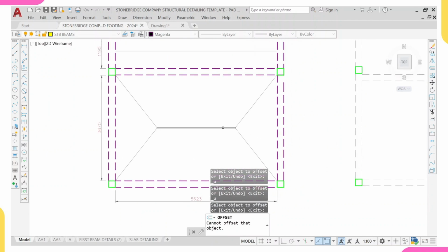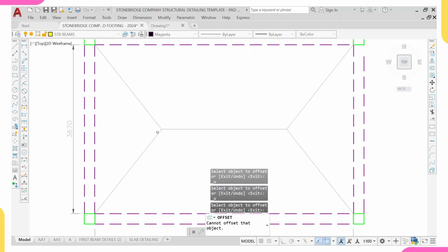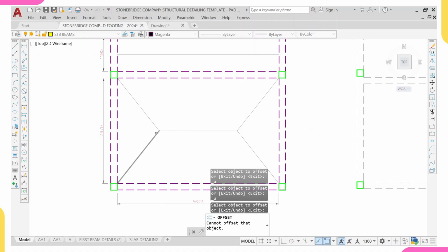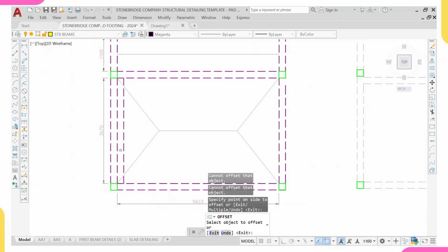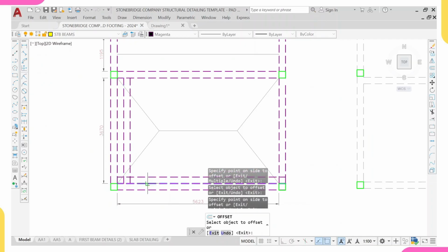So in a two-way slab, all the beams, this beam, this beam, this beam, this beam, are all carrying load. That's why in a two-way slab, in all directions, we will place main bars. But the bar that will be at the bottom is the one along the shorter end, which is this 367. This bar will be at the bottom, but it's still a main bar. This one will now be on top, but it is not a distribution bar because this is a two-way slab.